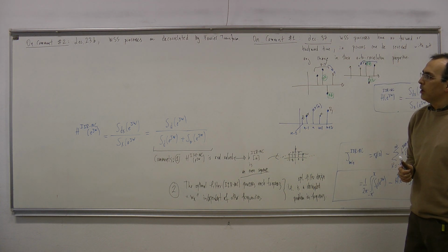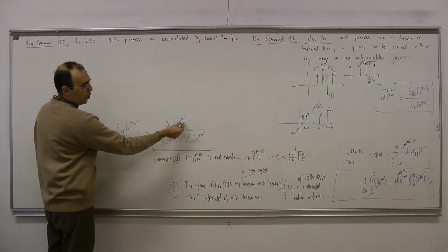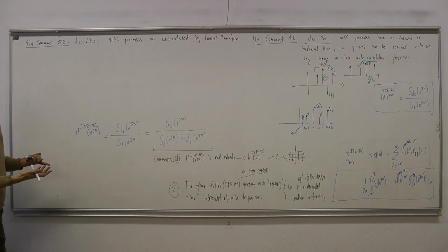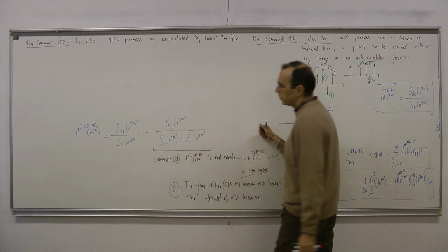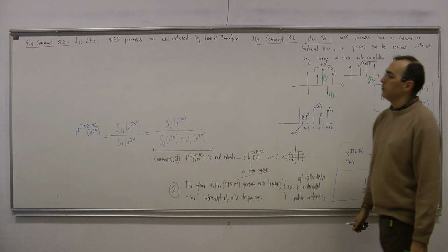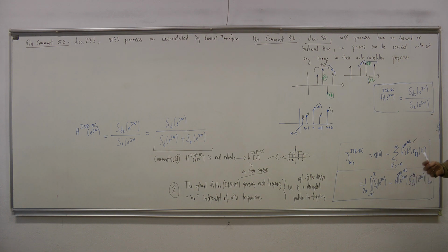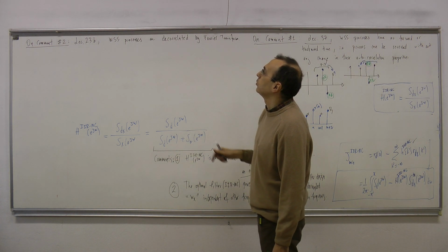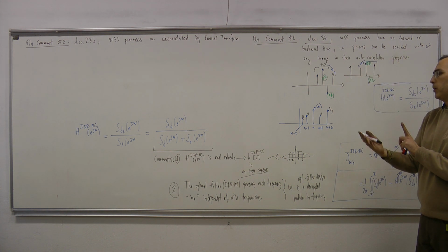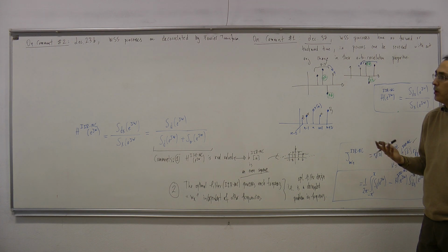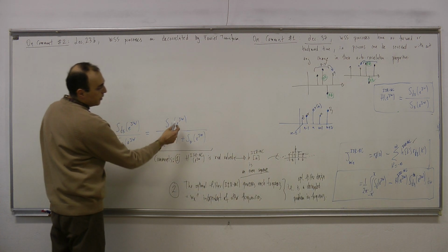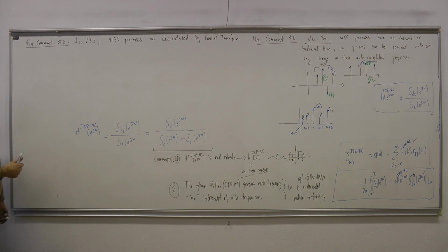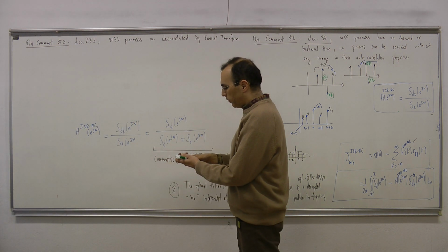So this tells us that if you have a random process, frequency omega x and frequency omega y are uncorrelated. Meaning that for the sake of linear prediction or linear operation or linear combining, whatever your purpose is, those frequencies do not carry any information with respect to each other. If the samples of the spectrum at different frequencies are uncorrelated, they don't carry any information about each other. So this is the reason that, for comment number 2, each frequency sample is just taken into account like that. So that is on comment number 2. So what's the meaning of this if we think about it?